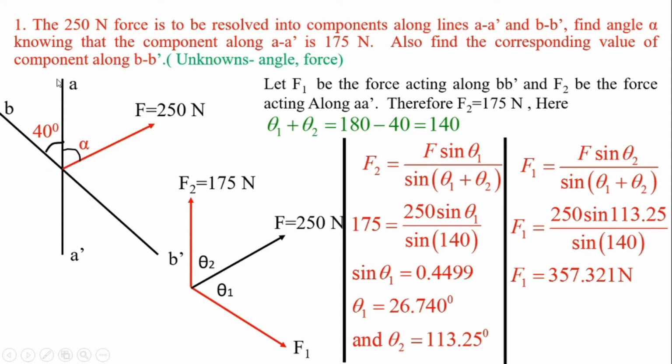If you observe the figure, these two directions are non-perpendicular directions, which means this angle is given as 40 and hence the angle between these two directions is 140. When the directions along which the force is to be resolved are non-perpendicular, the resolution is called skew resolution. So here we have to use the concept of skew resolution.